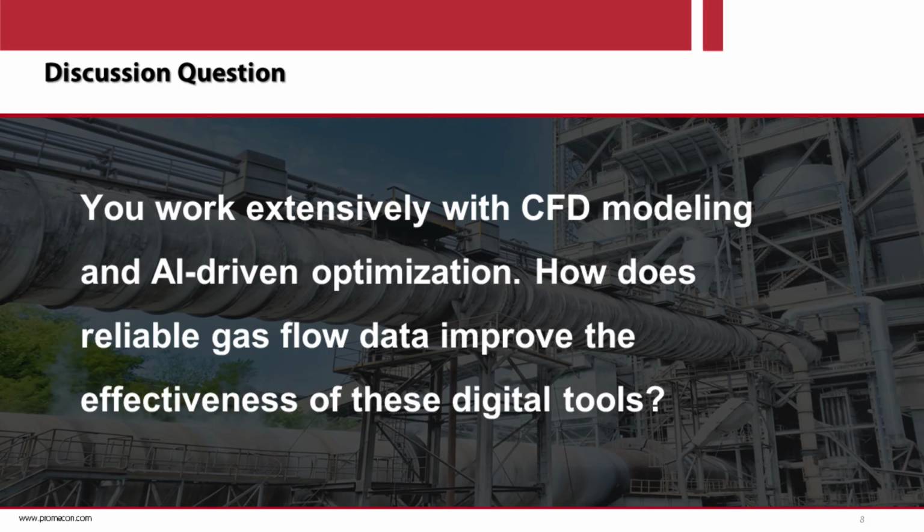But in particular for the airflows, because of a lot of noise in the process and in particular in the fuels, if you're applying alternative fuels, then an AI-based prediction of airflow rates, which is purely based on AI sensors, will most probably not work from my point of view.